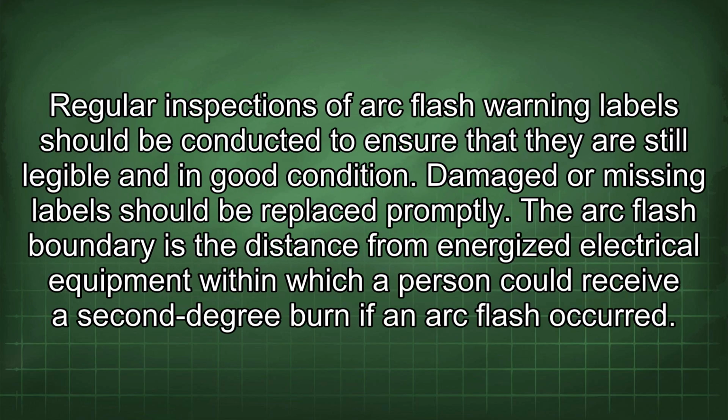Regular inspections of arc flash warning labels should be conducted to ensure that they are still legible and in good condition. Damaged or missing labels should be replaced promptly.